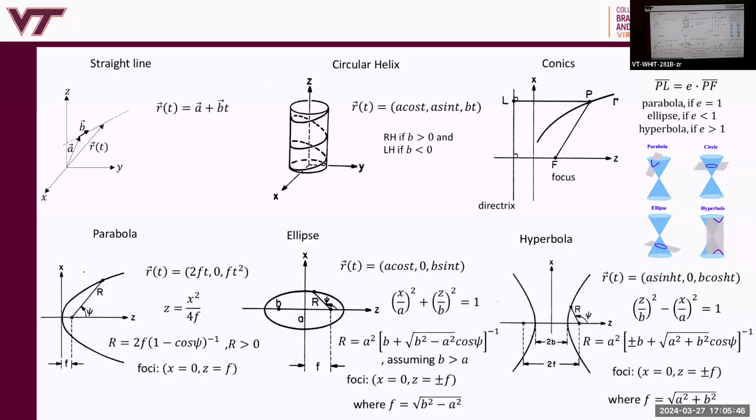You guys know the parabola, right? We know the property of a parabola is that every single one of these rays are the same length, right? If you go to some aperture, from focus to the aperture, they're all the same length. That means they're all going to have the same phase and the reflector collimates, right?